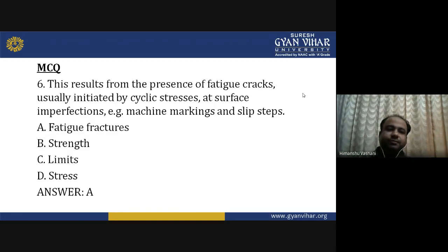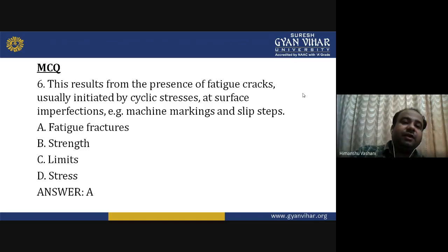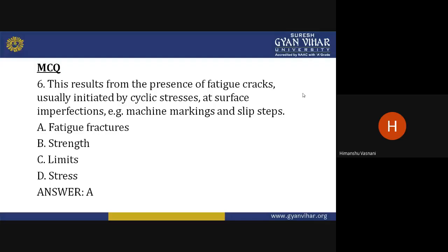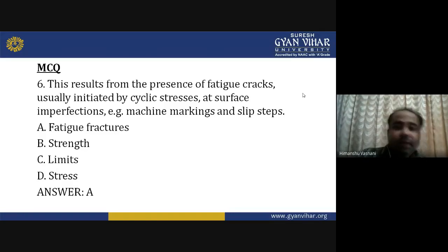True. Then, this results from the presence of fatigue cracks usually initiated by cyclic stress at surface imperfections, for example machine markings and slip steps. What do you say? Fatigue cracks initiated by cyclic stresses. So from that you can understand that this kind of fracture may occur.